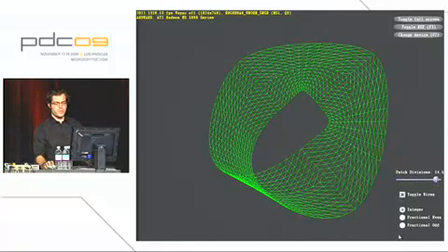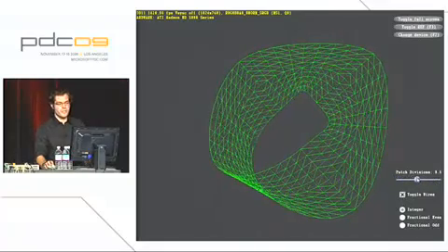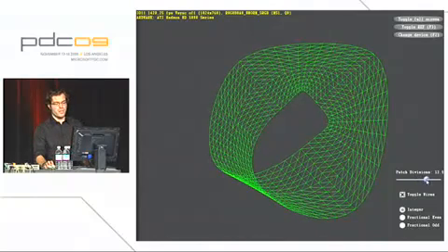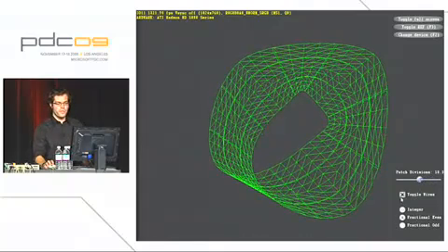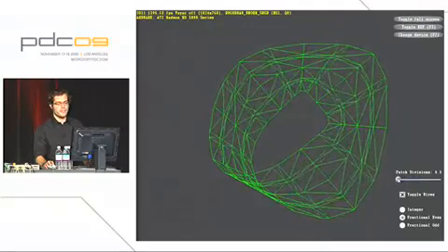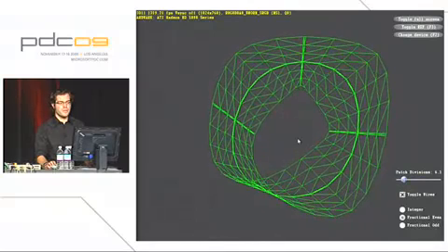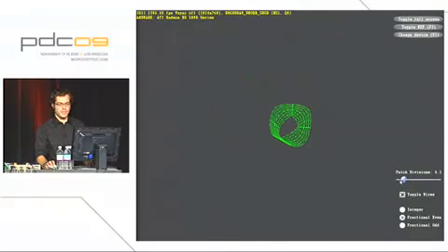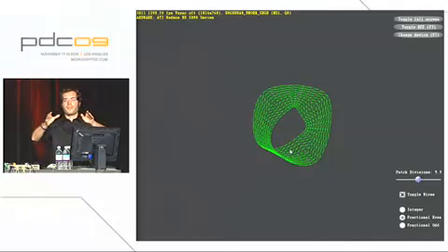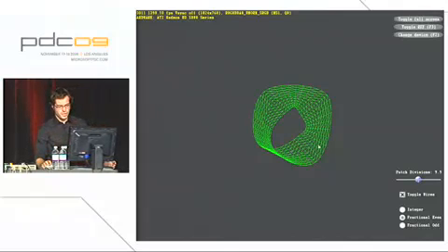Now, an important thing, you notice these 3 buttons down here. These show the different partitioning schemes that I have available. Right now, I'm on integer, and you can see that when a row of triangles is ready to be inserted into the tessellation scheme, it just jumps in. Well, I can choose one of these fractional systems, which will start to ease them in by expanding them out on edges. This is really cool because as the model zooms out, I can introduce geometry in a smooth manner so that you don't have this sudden jump as the model comes in. It smoothly interpolates the values as it comes in. That's really powerful.